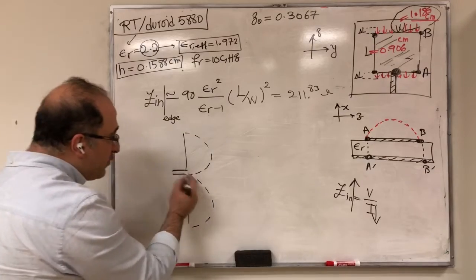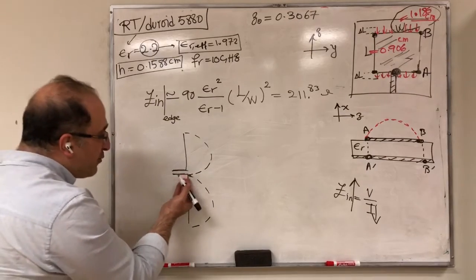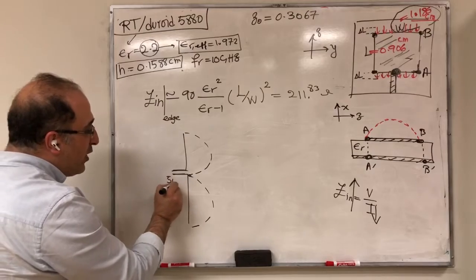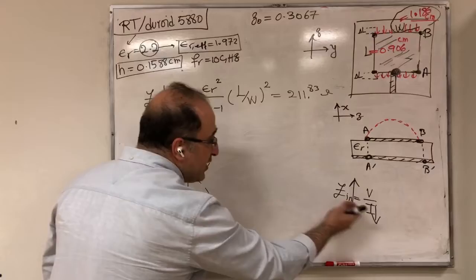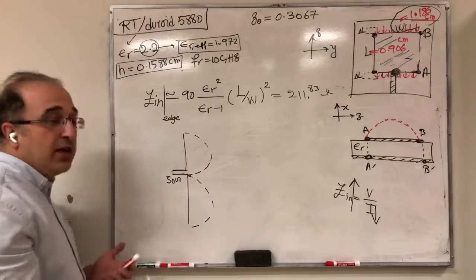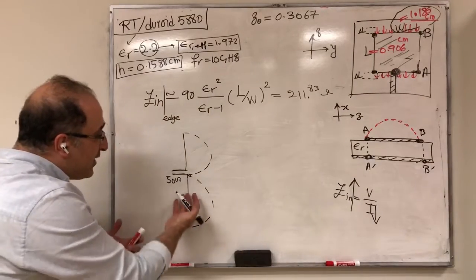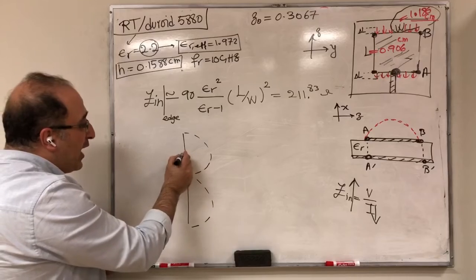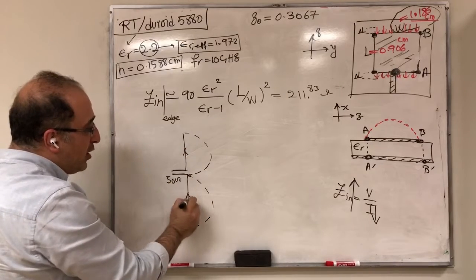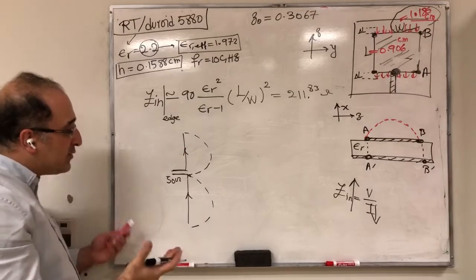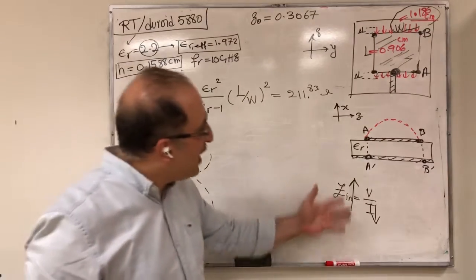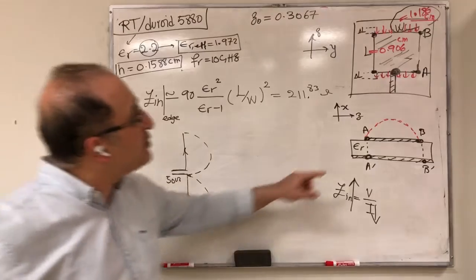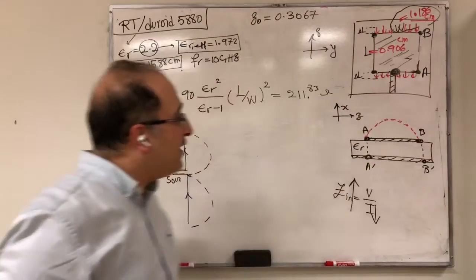So when you wanted to feed this antenna, you would have a problem, because then you weren't able to match it properly to 50 ohm, because I becomes very small, Z becomes very large, and you are in trouble. In terms of current, it was okay, as we explained before, that these are two sets of currents which are completely okay. This is the problem of power delivery. So we have a similar current, that current becomes very small at this point.